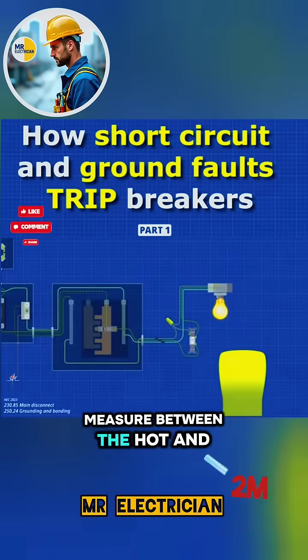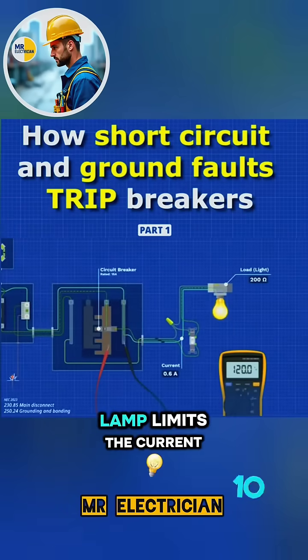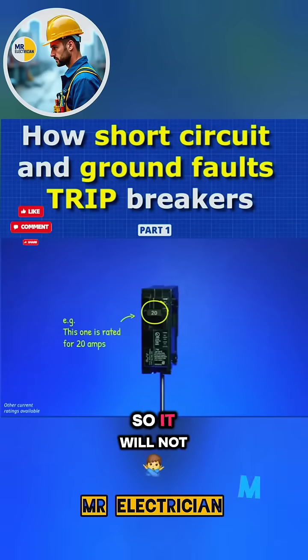If we measure between the hot and the neutral, we should read around 120 volts. The resistance of the lamp limits the current flowing in the circuit, and so only a small current will flow. This is much less than the rating of the circuit breaker, so it will not trip.